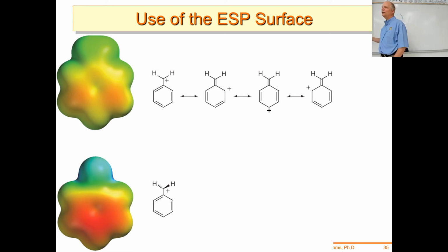Now, is this a stable structure? No, but you can do things that aren't stable in Gaussian. You can calculate transition states and hold them there and then calculate their electronic structure. This is something you could not do experimentally at all, probably, or if you were, you would be an amazing experimentalist in holding molecules and making them do exactly what you want them to do. But it's very easy to do this kind of thing in Gaussian.